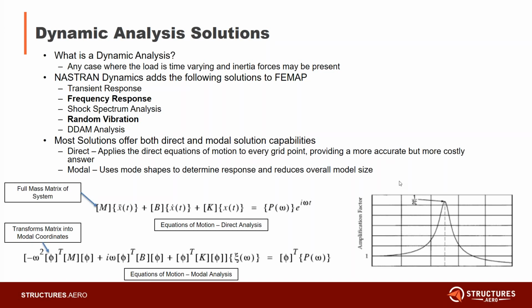So one of the capabilities added to Femap to allow you to analyze for these situations is the dynamics add-on. It adds several solutions: the transient response, which is a time history response; frequency response, one of our focuses for today, which is again response over a range of frequencies; shock spectrum analysis; random vibration, which is for non-deterministic events, where you're going to look at statistical probabilities of certain stresses or responses happening; as well as DDAM analysis, which is a specialized analysis typically used for naval or marine applications.